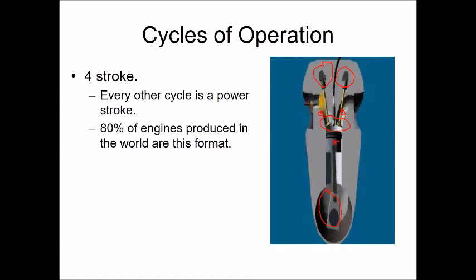So we're going to see a little video. We've got the 4-stroke cycle. As I said, colloquially, what we learn is suck, squeeze, bang, blow. But what we actually mean is induction, compression, ignition or combustion, and then exhaust. Those are the 4 parts of the cycle. We're going to look at them throughout the rest of the lecture in their real, non-ideal form, and then when we do the analysis in the subsequent lectures, we will look at them in their idealized form so that we can do some thermodynamic analysis. So let's take a look at the video. Again, watch it carefully, make sure you know everything that's happening in there.